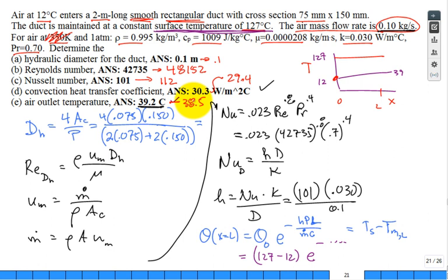So if you're doing something in Wiley Plus and you really didn't know what fluid temperature to use to evaluate your properties, now you know both the inlet and the outlet mean temperature of the fluid. If you didn't get the right answer, and it's probably off by 2% or more, then try to reevaluate your fluid properties and repeat.